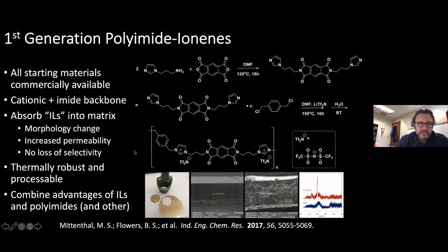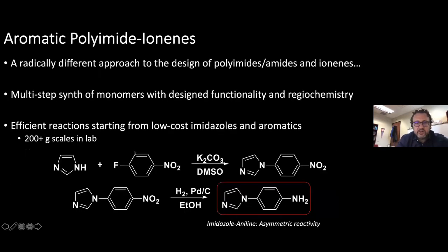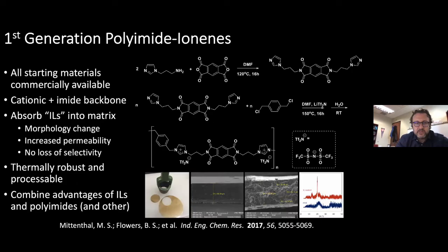So here we had an interesting result that gave us some good membranes, right? We saw too, I don't have the data on here, that when the ionic liquid is present, it increased the permeability, the CO2 flux of the material, about 20 times compared to the material without the ionic liquid. So the ionic liquid's making a big impact on the performance of this material.